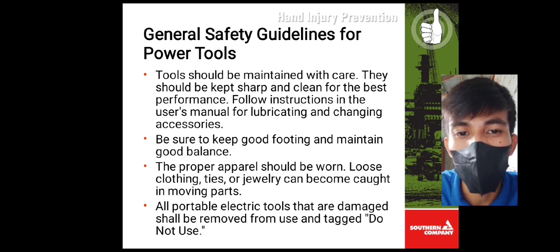Be sure to keep good footing and maintain good balance. The proper apparel should be worn. Loose clothing, ties, or jewelry can become caught in moving parts. All portable electric tools that are damaged shall be removed from use and tagged "Do Not Use."